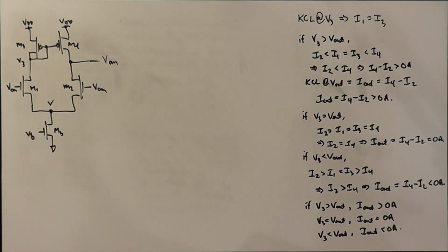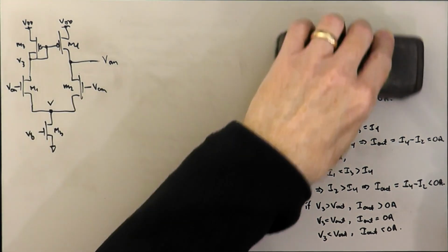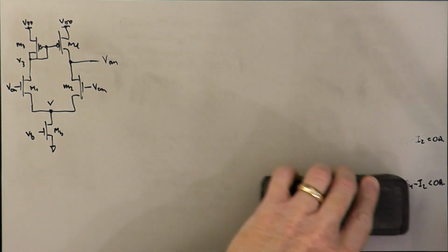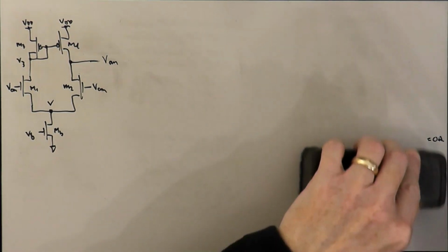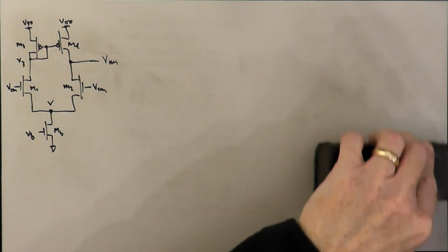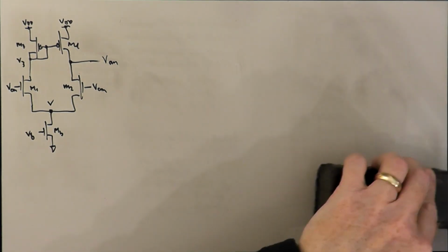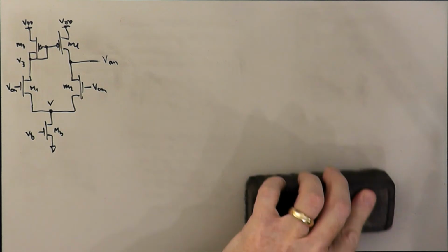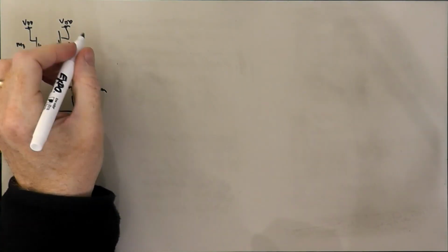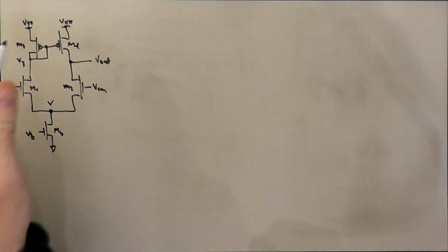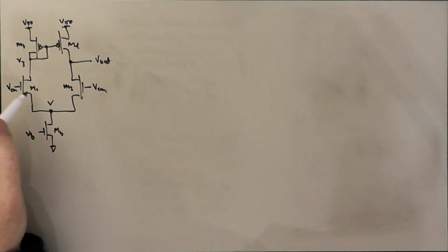And we're going to use this notion that V out basically does, in the pure common mode case, okay, please don't get confused into thinking that this idea that V out is always equal to V3, that's only true for this balanced configuration where V1 is equal to V2 equals a pure common mode input signal.